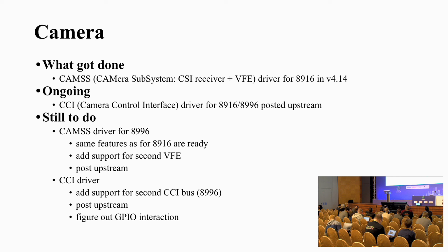And then when I was reading the hardware documentation, it seems like there are two I2C masters, and then there is a GPIO driver engine thingy where you can configure GPIO interactions to either run independently or synchronized with I2C operations.